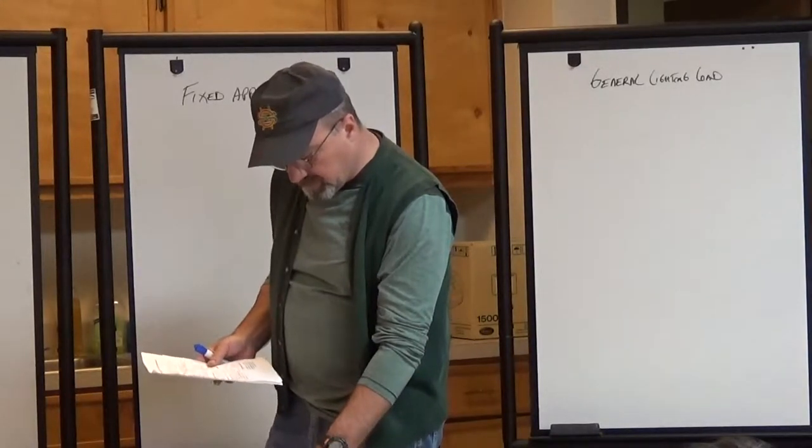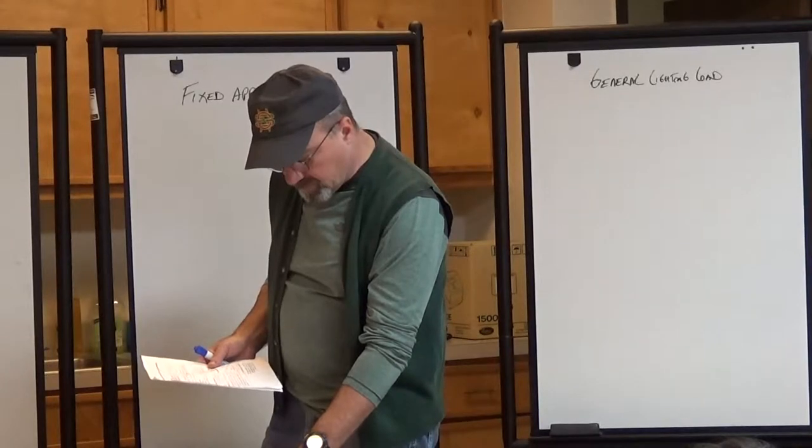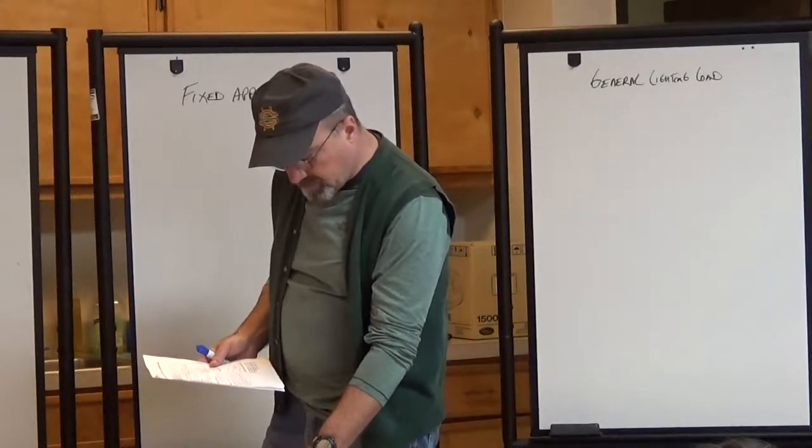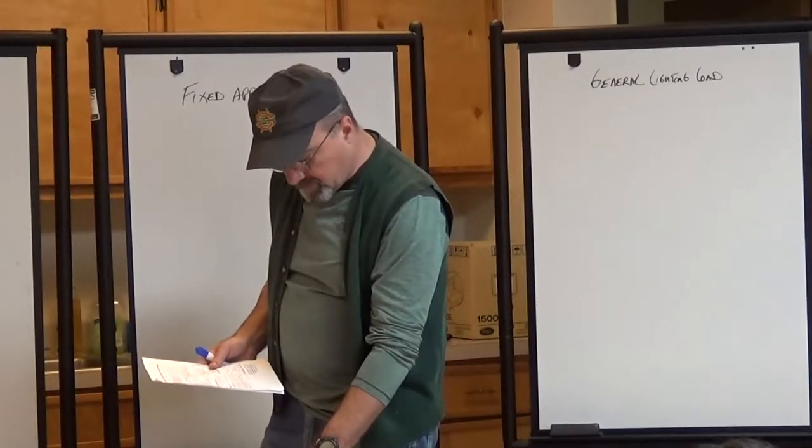A unit load of not less than that specified in Table 220.12 for occupancy specified therein shall constitute the minimum lighting load. The floor area for each floor shall be calculated from the outside dimensions of the buildings, dwelling units, or other area involved.